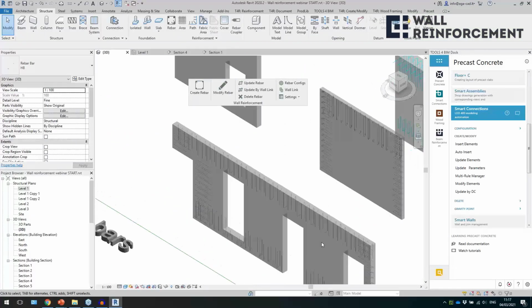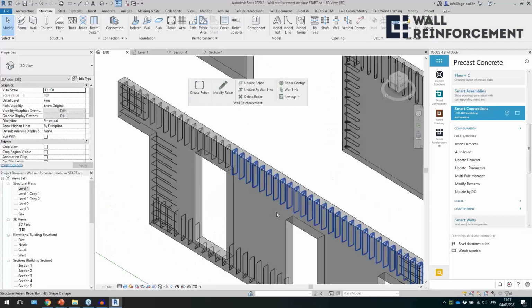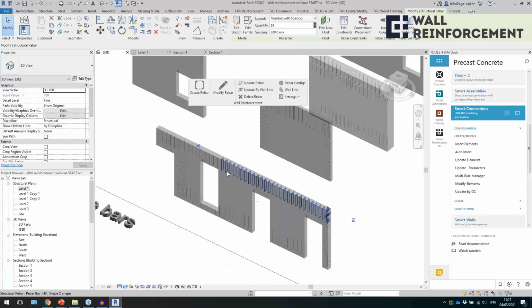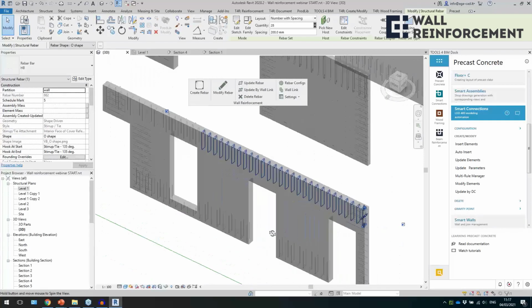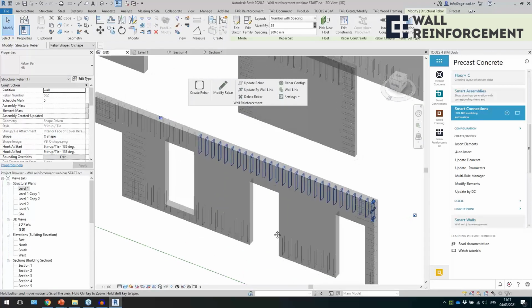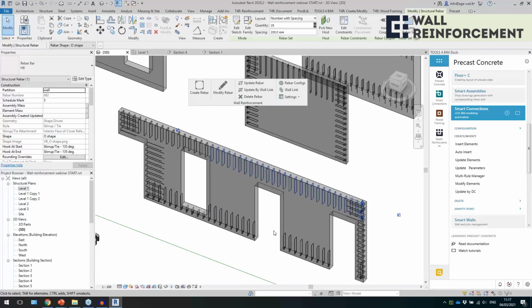But then I have O-shape bars. So again, I had this in perimeter, but I have more control now, to meet different kinds of situations. For example, here I have O bars at the top, at the bottom, but U-shaped bars just at the ends of the wall.